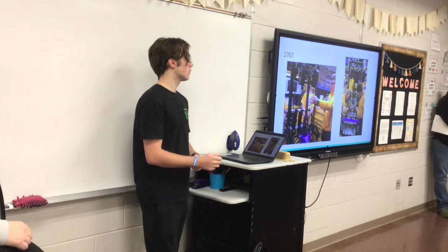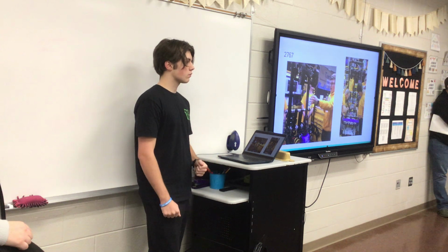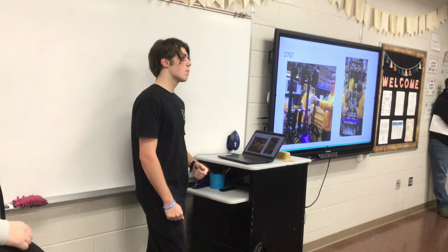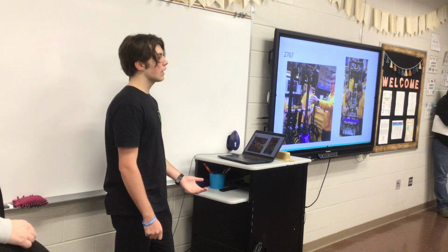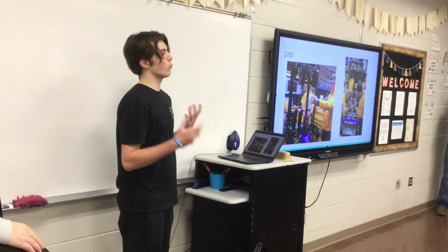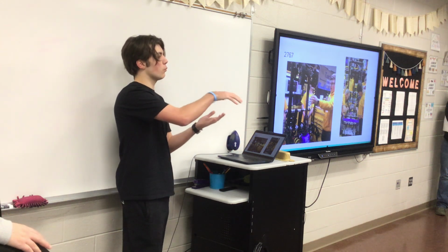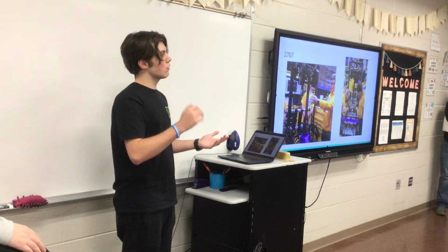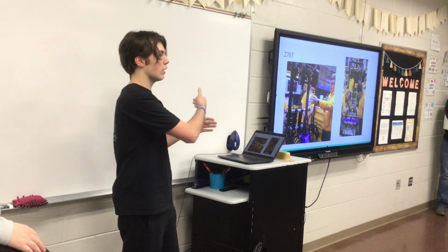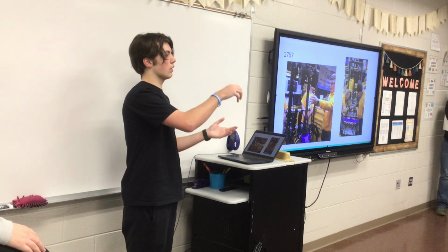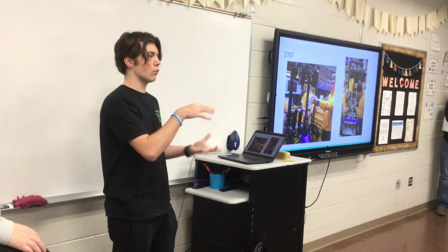When making a thicker sheet, is there an advantage of stacking different weaves on top of each other, or is it better to use one weave throughout? When stacking sheets like that, we tend to use one weave, but we rotate it, so that as force is applied, it doesn't share the same weakness in every direction. If you stack it all in one direction and it has a weakness, all layers have that weakness. But if you offset it by 90 or 180 degrees, the weakness is spread out instead of in one area.